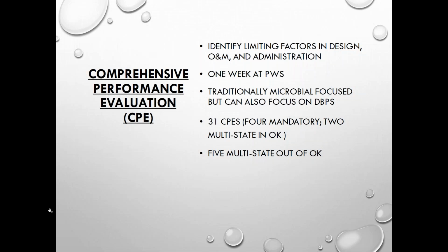Now, I talked about a small part of AWOP that is enforcement, and that is the CPEs. You can have a mandatory CPE triggered, and it's a mouthful for that trigger, but if the same filter exceeds 2 NTU in 2 consecutive 15-minute periods in 2 months, that water system has triggered a mandatory CPE. So we try to do as many voluntary CPEs as time allows, so we're sharp and up to date on the process if a mandatory CPE is triggered.